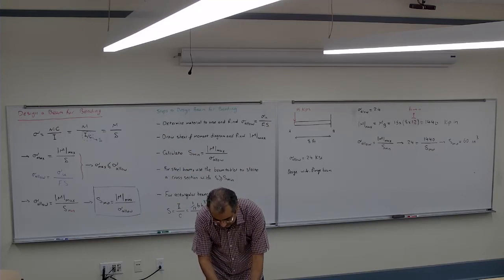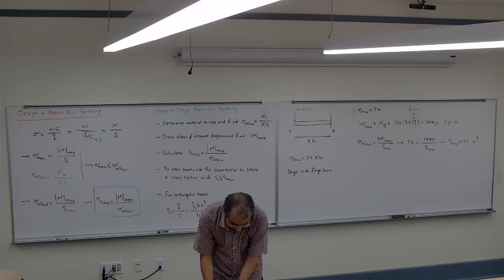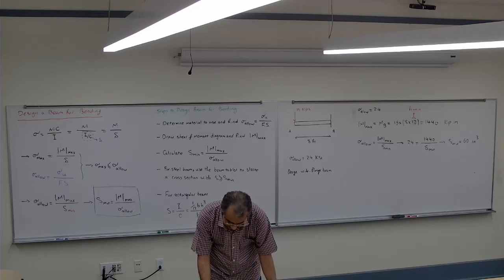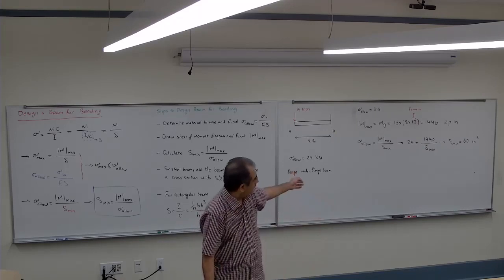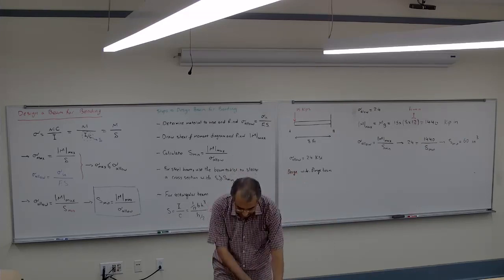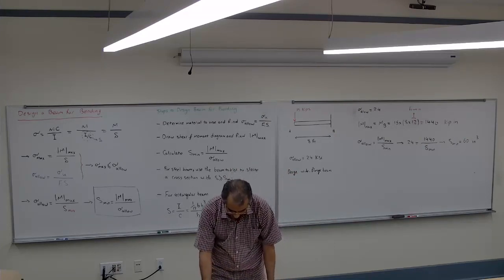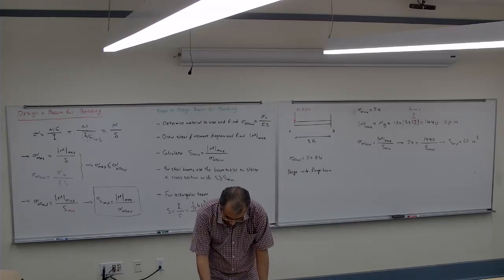The closest one we have is an S of 62.6. Make sure they're using foot-inch. Yeah, it's in inches cubed already.